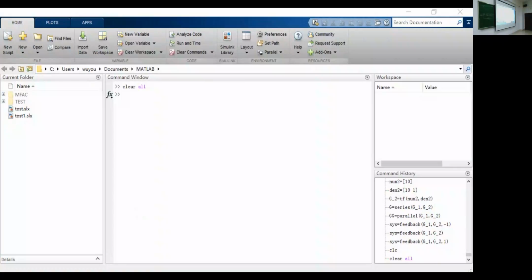But don't forget one more thing as well, feedback. Then how to connect the feedback line? First, you choose the line here and then click the right button and drag a new line here and directly to here. Right? And it shows k equals 1 here. It's just equal to a straight line. For example, if it is 3, okay.